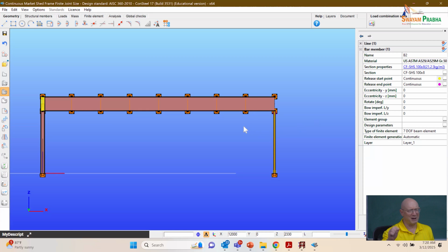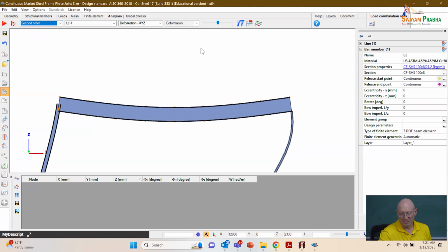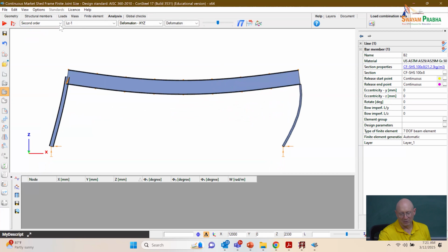So I'm saying, hey, I've got an end plate connection of that HSS section to the bottom of the girder. I think maybe that's closer to a continuous detail than a pinned one. So that's what I'm thinking for my idealization. Let's run the analysis. So if you run the analysis that we've set up here, clearly that HSS section, let's do second order.